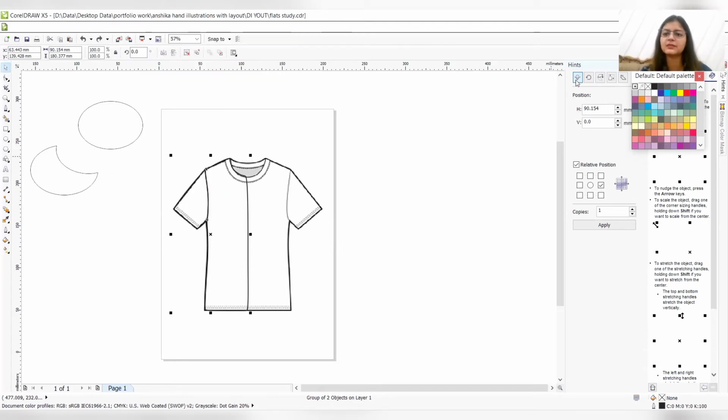What you will get is this plus sign here. Sometimes, for those who don't know this method, if we want to make a copy, we just press the plus sign on our keyboard, but that's totally wrong. Here we should select the height, the verticals, the relative position, and according to that we should replicate it.